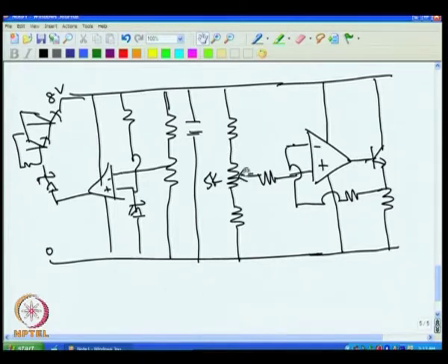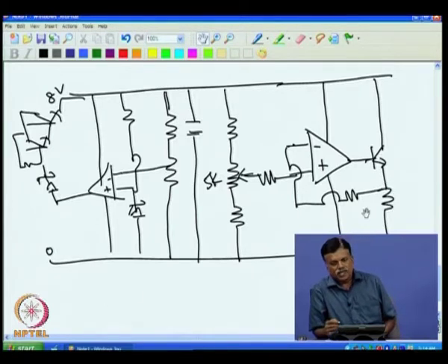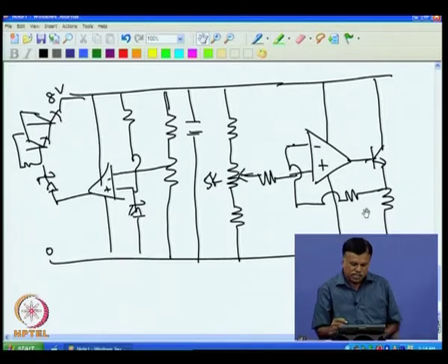So you only get a 1:3 variation in voltage, but the current variation required would be around 1 milliampere to 17 milliampere. When the input is around 2 volt, you need 1 milliampere; when the input is around 5 volt, we need 17 milliampere. That is roughly a 2.5 times variation in voltage for a 1:17 variation in current. That means it becomes a non-linear variation, and that is not acceptable. It has to vary linearly with the position here.